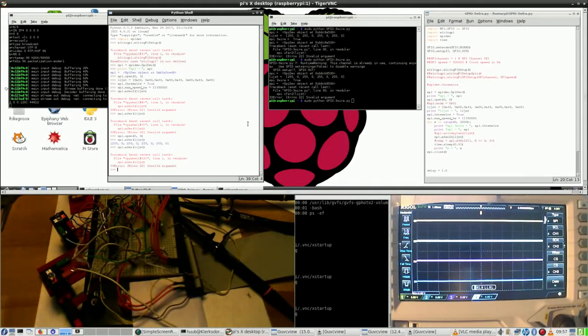And unfortunately, I saw no signal going. It may be that this time base is set too high with 1 millisecond, but on the other hand, I did not see any disturbance whatsoever. Remains the question why it works once and then no more.